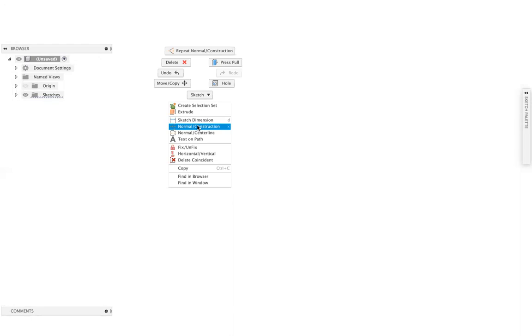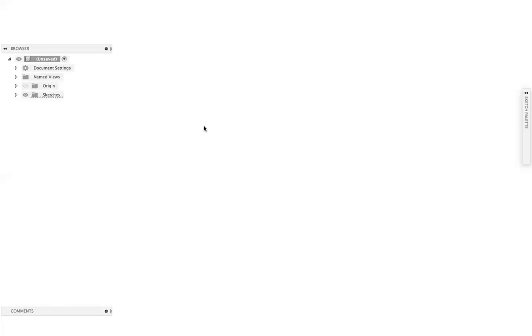When you click down on the wheel, you can rotate your shape, and you hold shift and click and you move it around. So instead of pinching and pulling and sliding with 2 fingers, it's a really nice way to navigate your models if you have a mouse. And then when you have the mouse with the keyboard shortcuts, you start getting really efficient and you can build these things pretty quickly. So yeah, let's go to normal/construction.